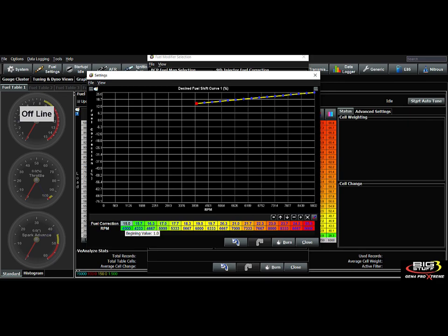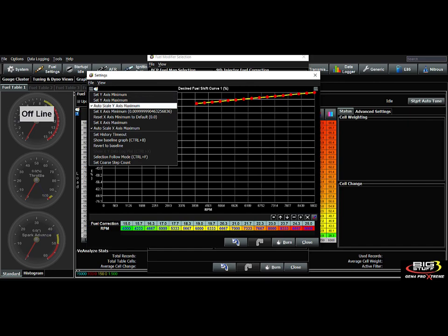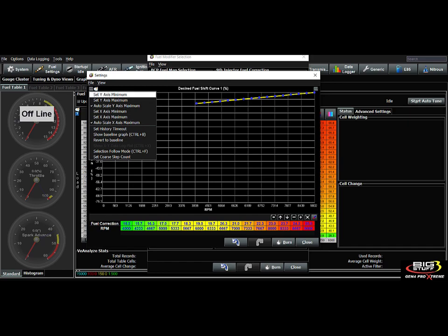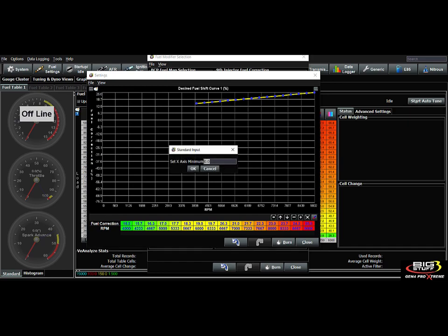Okay, nothing will start until 4,000 RPM. Then I'm going to start pumping in fuel. Okay, we talked about how to change all these other curves and make them look different here. So sometimes you can reset these guys and we can make it look better. But for example, if I made the minimum, instead of 0, 4,000, we can get this graph to look better here.